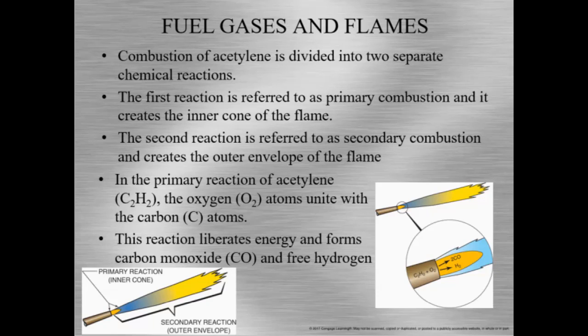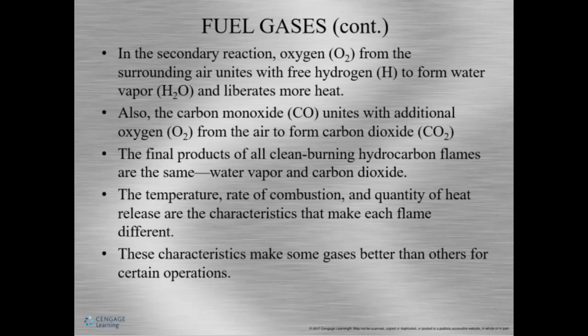The second reaction is the outer envelope. So this is primary, and this is secondary. Pretty cool. In the secondary reaction, the oxygen from the air unites with free hydrogen and forms water vapor, and it makes more heat. The reaction also has the carbon monoxide united with other oxygens, and they make carbon dioxide. Ultimately, the final products of the hydrocarbon flames are the same: water vapor and carbon dioxide.